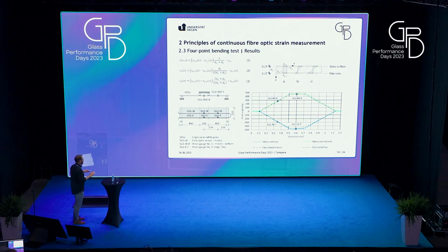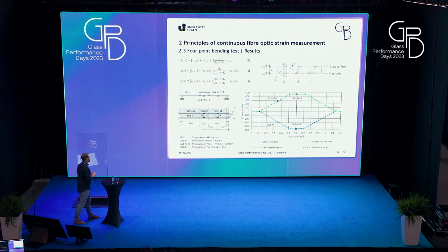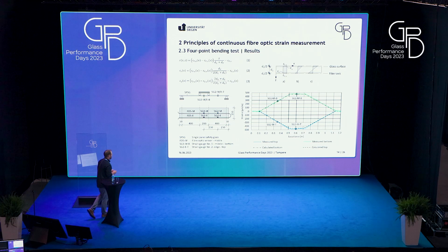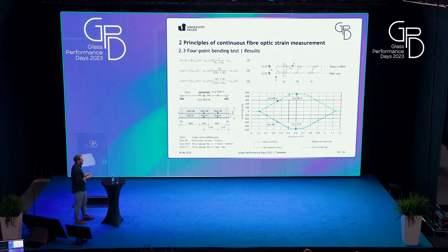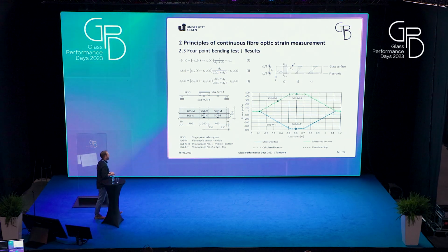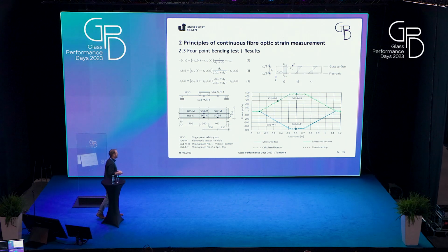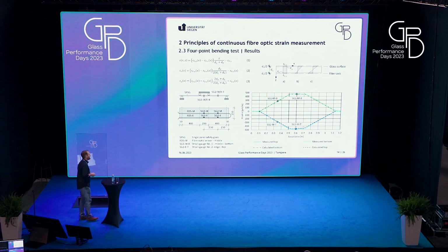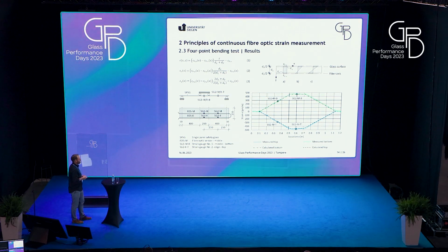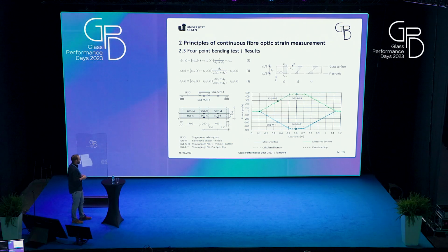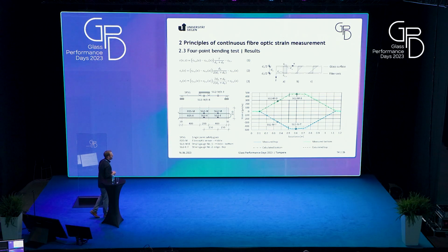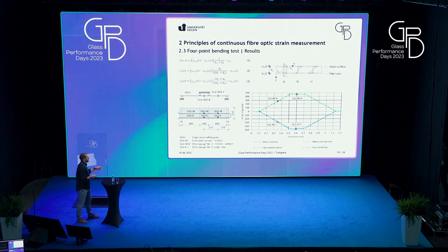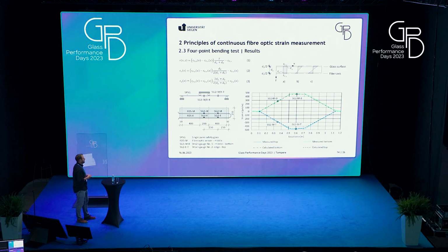We have in-between measurement on the surface of the laminated glass beam, and the results were shown in the graph on the right. The green line shows the tensile stress, and the blue line shows the compression stress. You see that it matches very well to the calculated values that are shown with a dotted line in the picture.